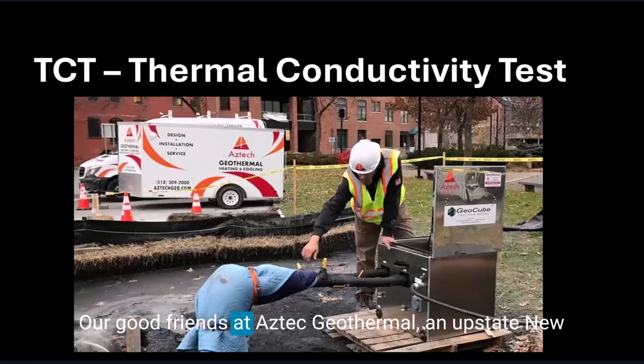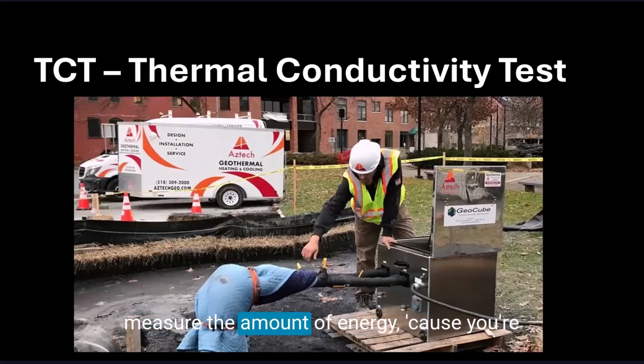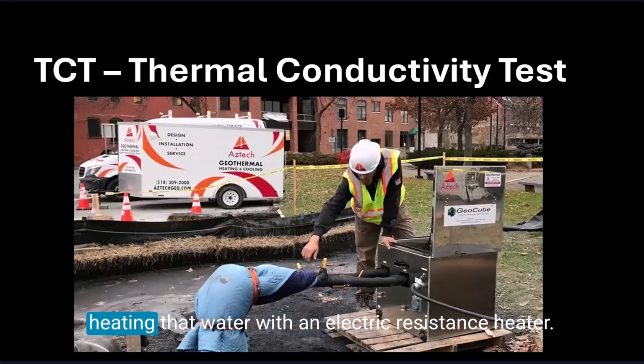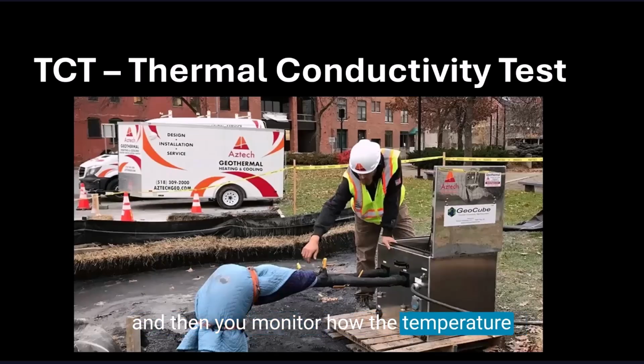Our good friends at Aztec Geothermal, an upstate New York company, do thermal conductivity testing. It's pumping heated water into the ground. You measure the amount of energy because you're heating that water with an electric resistance heater. You've got a flow meter. You're circulating that heat so you know exactly how much heat you're putting into the ground. And then you monitor how the temperature changes, typically over a 48-hour period.